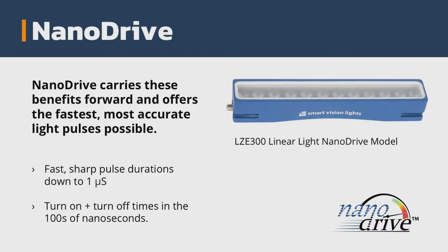Even though LEDs are very fast, how fast they turn on or off is a function of how hard you drive them. And even though for most things you would say an LED is fast, when we start measuring down in the microseconds of exposure, you can see that it takes between 2 and 5 microseconds to turn on the LED.